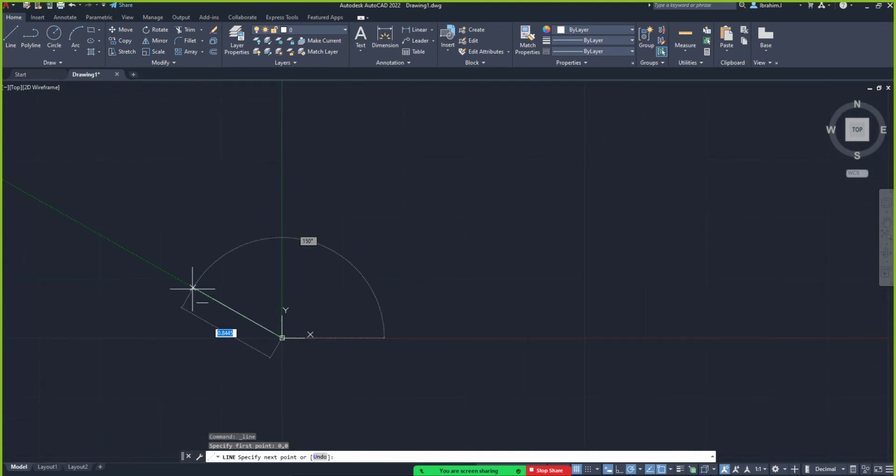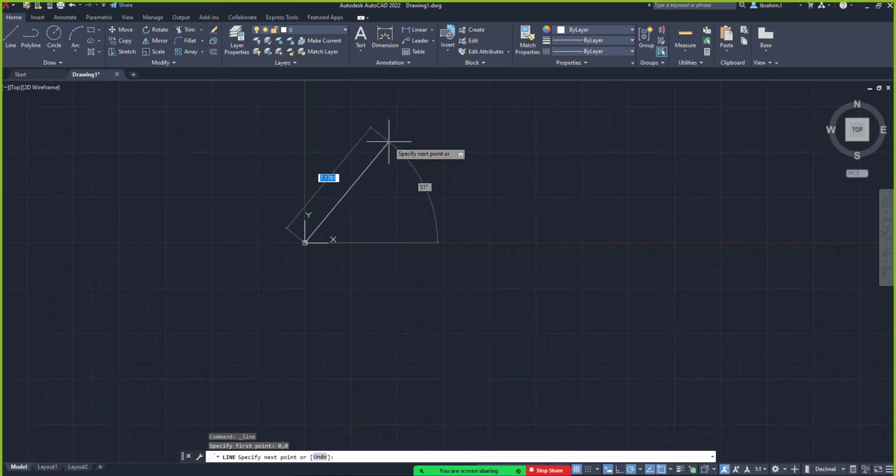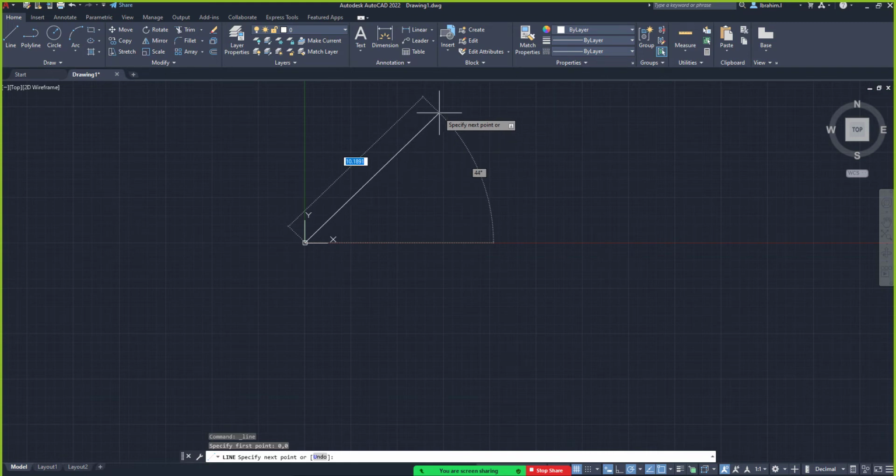Where we have the WCS. Can you see the WCS for the XY axis? From that point is where we have the 0, 0 for the X and Y axis. And then from there, we can start drawing whatever we want to do. If you want to tie your design to origin, that means it needs to be from what? 0, 0. Are you with me?